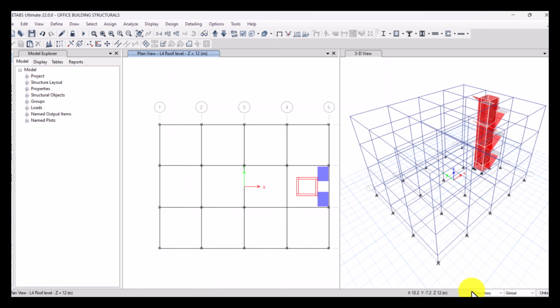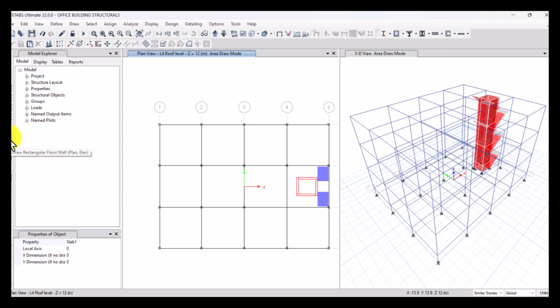So I'll come to this one, change this option of one story here. I put two similar stories. Then I'll come to slab, this option of a complete rectangle. I'll change the type to 400 millimeter ribbed slab. Then I'll come to the first corner here, drag onto the second one. Oh, sorry. I need to be on the first floor, which is the master story.